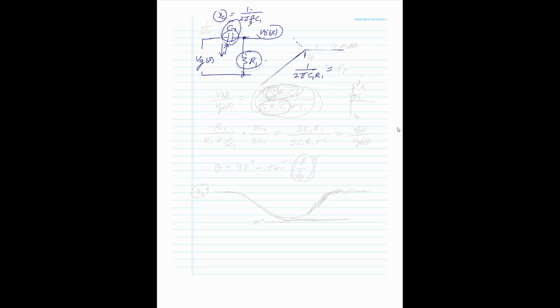And what has to happen is there has to be a pole, in a sense, coming down, which is this pole coming down, which means that this is a pole. That's an FP. Okay? So therefore, what we have, and what is this magnitude? As this goes higher and higher, this goes towards a short circuit, and the output voltage is equal to the input voltage. Therefore, it's 1 or 0 dB, converting it to 20 log of 1, which is 0 dB.